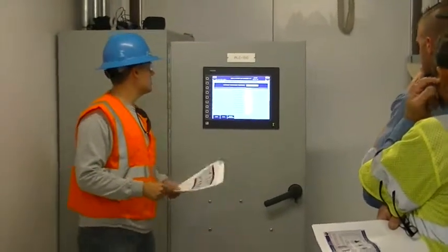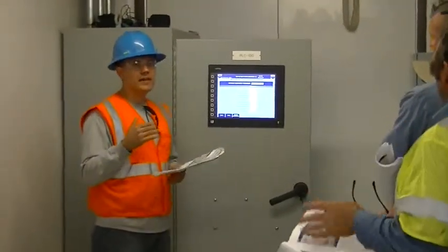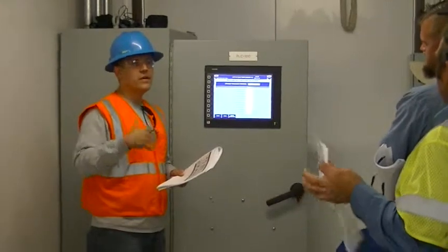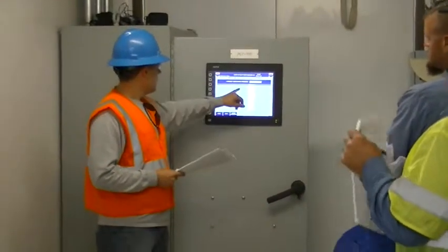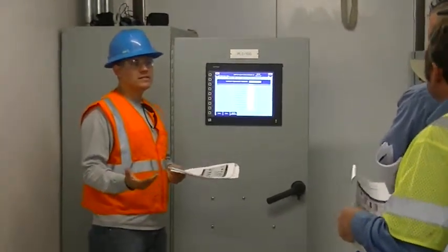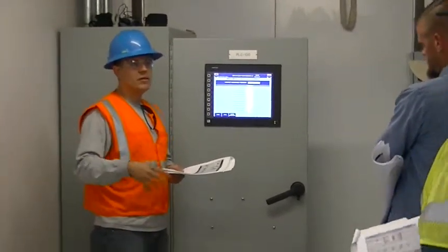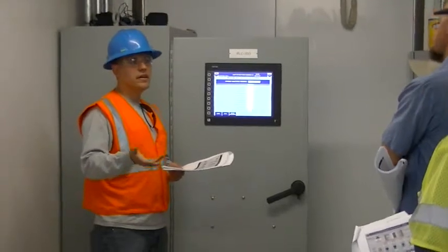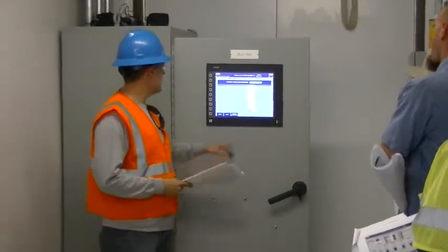So when your pressure drops below the 60 psi, that's when it's going to turn on the VFD. You have your lead start delay and lead stop delay. I put that to 0 seconds. That'd just be the time after I hit the set point that I either start, and then the delay of stopping it, if you guys want to do so.